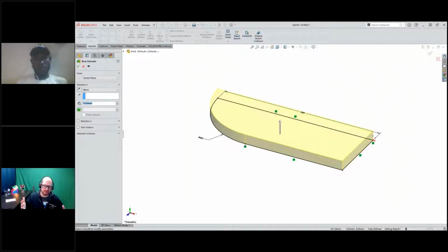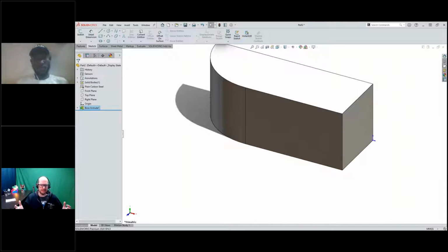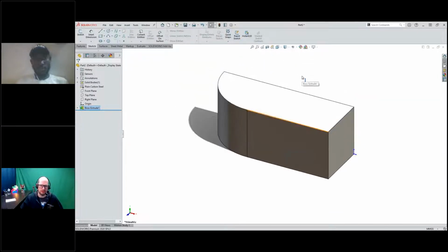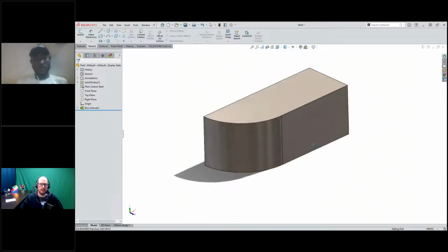And when we're in the extrude command, we can also use some shortcuts. One of my favorite shortcuts is I don't move my mouse anymore. I just immediately start typing. So I'm going to type in 60, enter, and then enter one more time. And now I have completed that extrusion. So now we've completed that boss going up to the desired height there. Those are some good shortcuts to remember, and I'll review some of these shortcuts at the end. But for now, I'm going to go on to my next sketch.